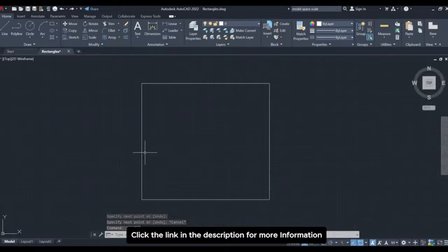Limits basically define the drawing boundaries or the extent of a drawing area. Basically, they establish the maximum X coordinate and the maximum Y coordinate that AutoCAD should consider when displaying and plotting an object. So by setting appropriate limits, you can ensure that the drawing remains within this area and prevents you from drawing an object beyond the desired boundaries.